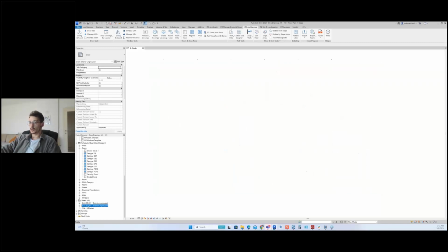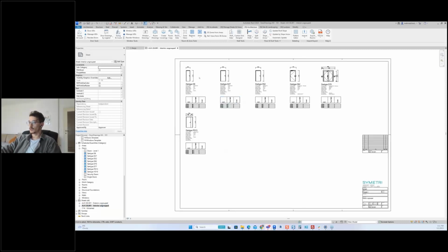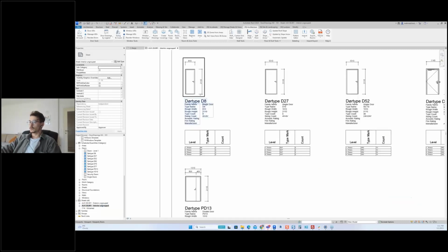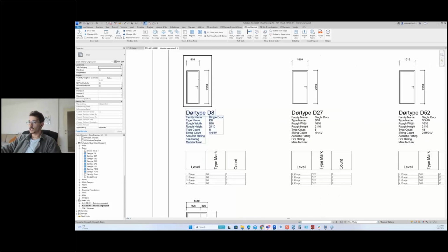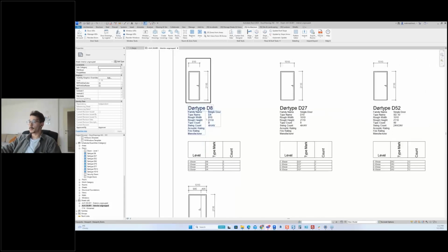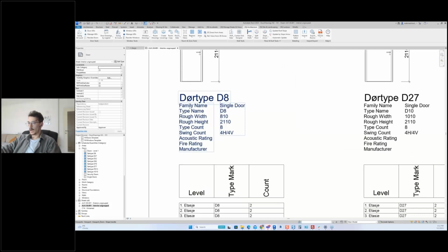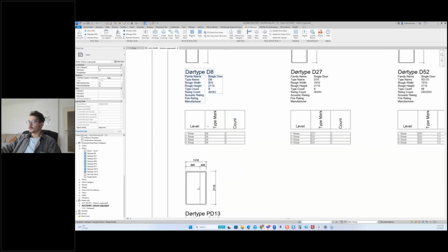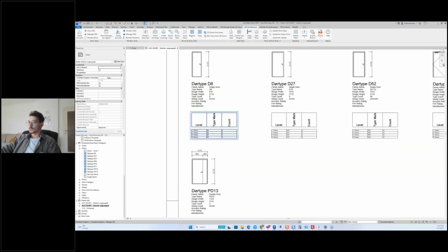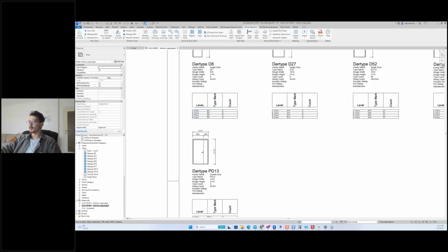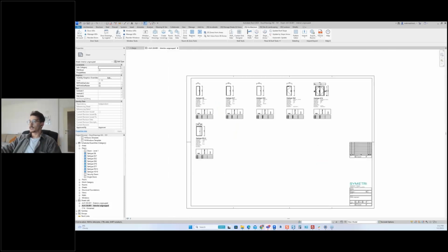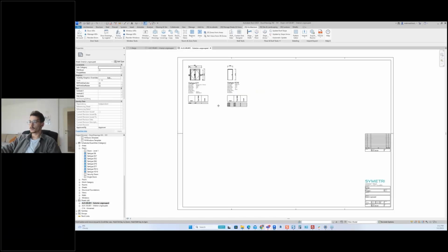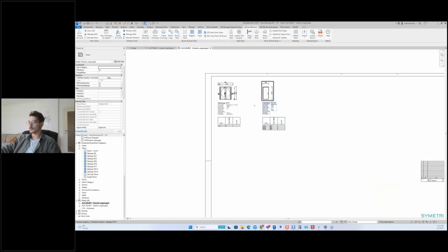So if I go to the interior doors right now, this is what we got. So the legend component is placed on the sheet, dimensioned, and the properties that I showed you last are shown in the view title. And then again, the schedule that we have defined to create has been created and placed on the sheet. So these are the interior doors, and let me just show you the sheet for exterior doors, there were only 2 doors that are exterior doors.